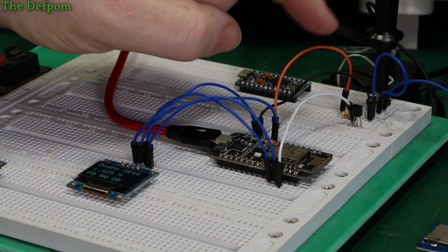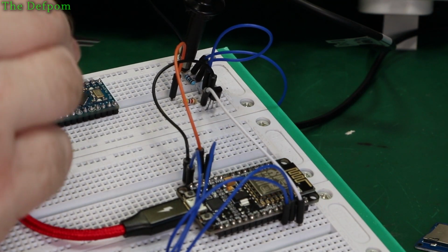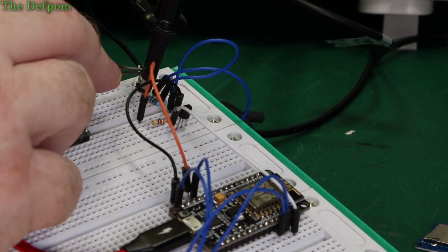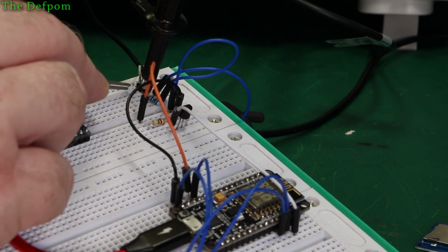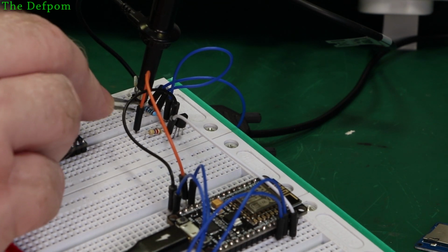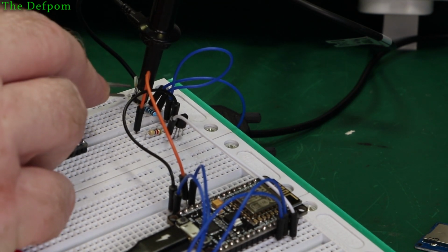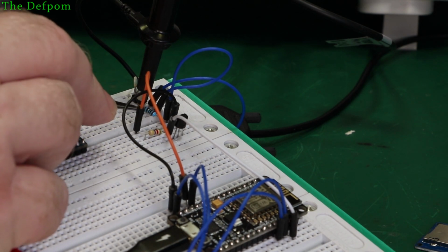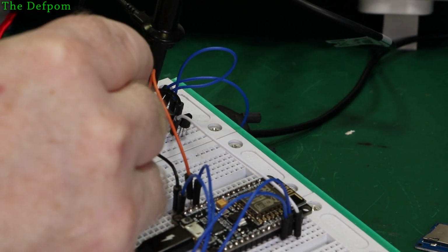What I've got here is a 3.3 volt line coming over, so we have this little jumper block on the back here, a 2-pin header, and the back comes in. That's the signals coming from the box. So you've got a resistor here, which is in series with the output from that device. That's a current dropping, voltage dropping resistor. That feeds the base of the transistor.